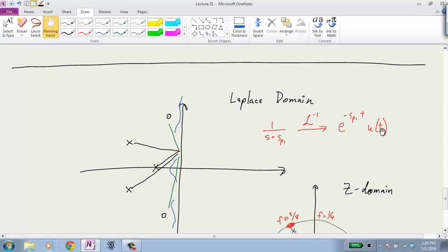Okay, so what this means is just by looking at this, I can say, oh, in the time domain, the impulse response, if these poles are very far from the imaginary axis, that means their real part is very negative. Have I done the negative signs right? Yes. So that means the real parts are very negative. That means it's going to decay very quickly.